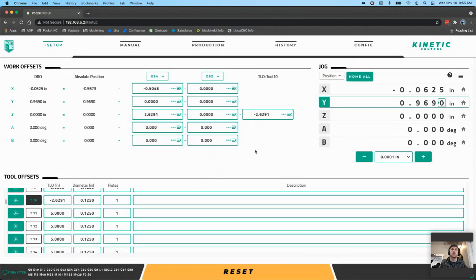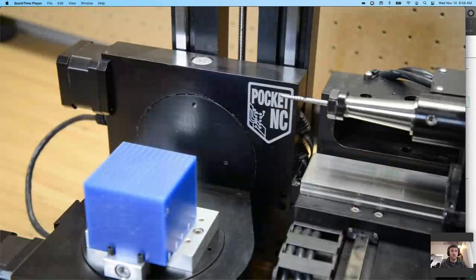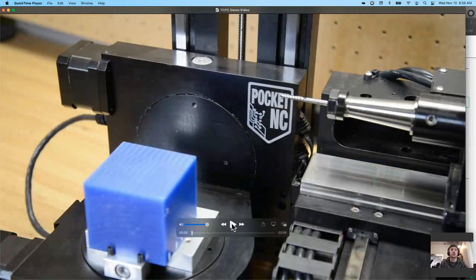Before, in order to do that, you had to actually run a small chunk of G code in the MDI command. So we've simplified this significantly by making this button available for activating a tool before setting those work offsets. The reason this makes it easier is that if we move our part in our stock or in our fixture, all we have to do is change our work coordinate system or work offsets in the UI. I've actually got a video here to represent that, so I will run that now and talk over it as we go.